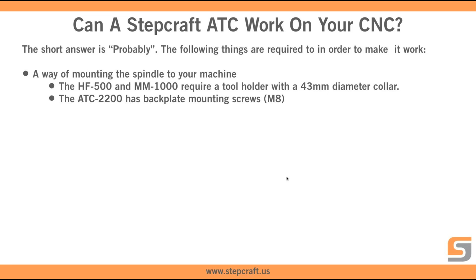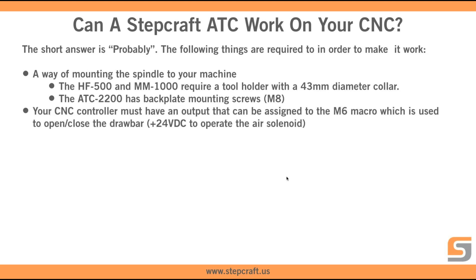So there's 4 M8 bolts that anchor it to the Z-axis, and I believe they're 100 millimeters apart from the left and right, and 100 millimeters apart up and down. But I can certainly get you those exact dimensions so you can mount it. But it is a direct bolt-on through the front into a backplate. In our machine, it works out nice because we have T-tracks, so I just use M8 T-bolts or T-nuts in there, and that's how we anchor it.